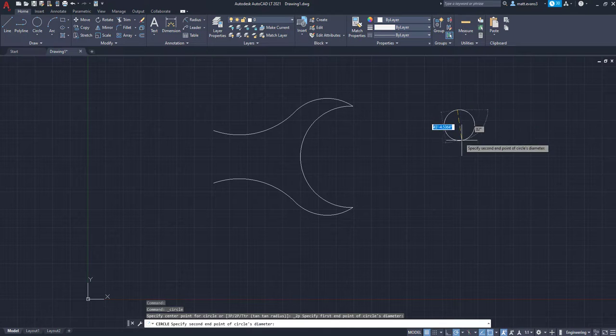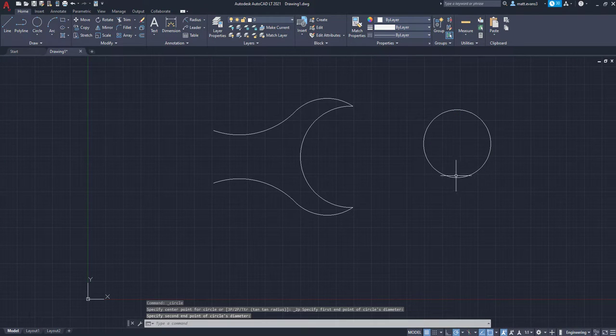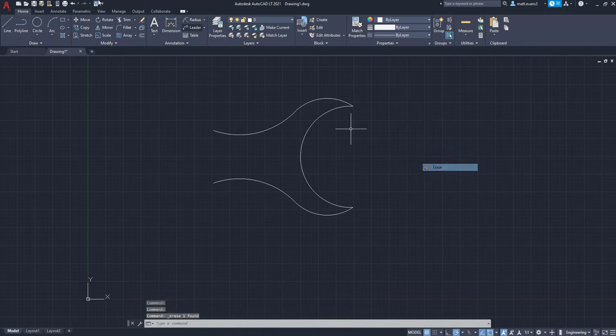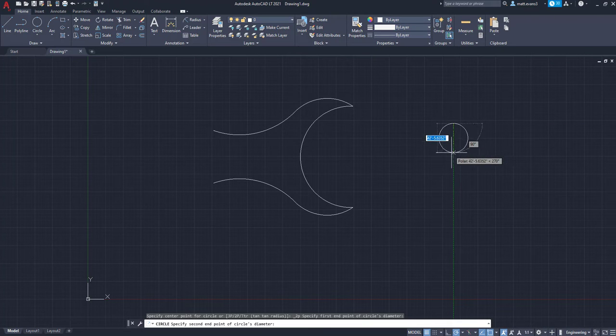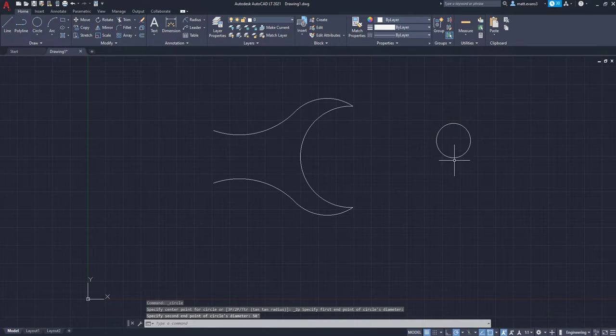We're going to left click right here, and then it's going to bring me down to my second point. And as you can see, it created the circle. So we're going to erase that. Here we can also create 2 points based on size. So for example, we want it to be 50 feet. We're going to bring it down, press enter, and it's going to be 50 foot. But in this case, I'd rather use the diameter versus the point to point.